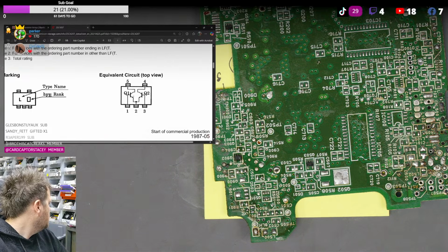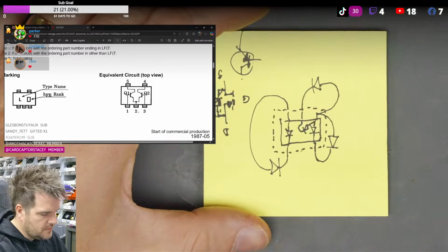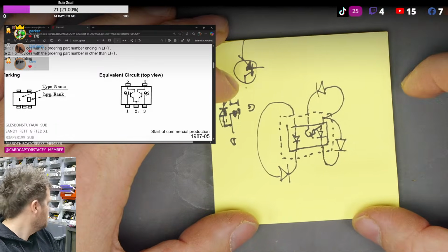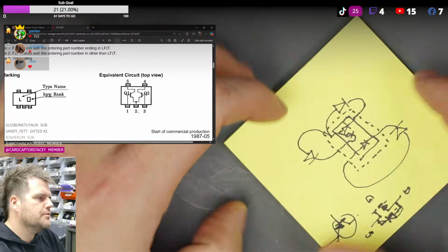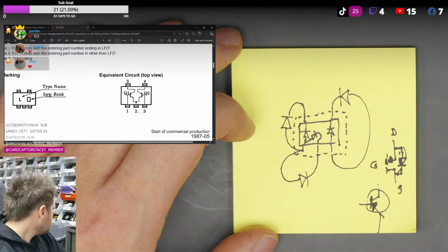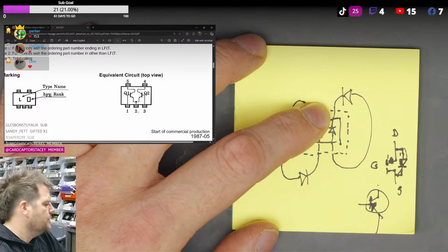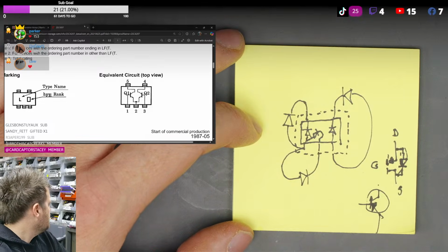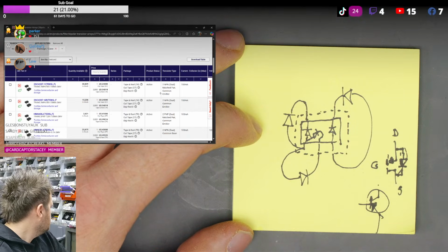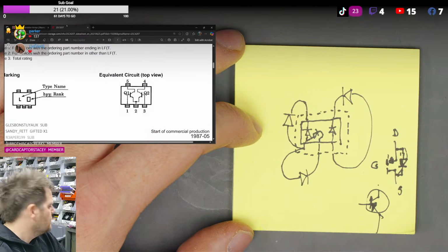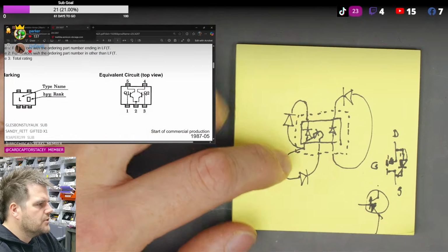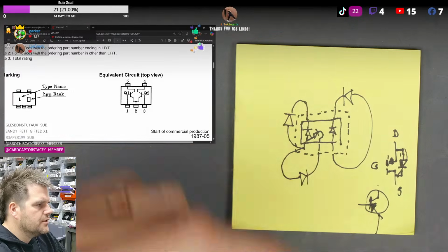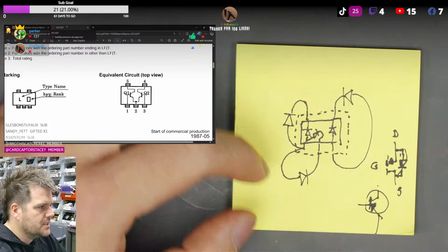Pin 2 and 3. All right, so let's look at this again. That's the orientation most data sheets are in. There'd be a diode flowing this way, which there isn't, because that's going to be a base, so it's not going to be that one straight away. So it's not a 2 NPN dual match pair. Let's try a common emitter. Now the thing is, we've got one common and the others aren't common. This almost seems isolated.